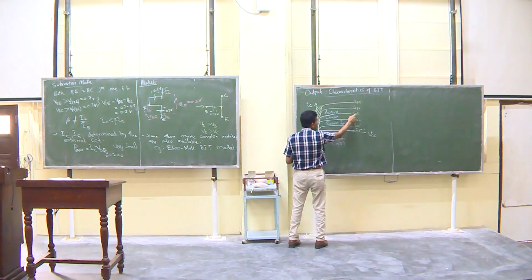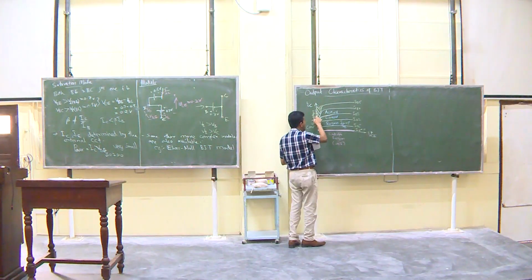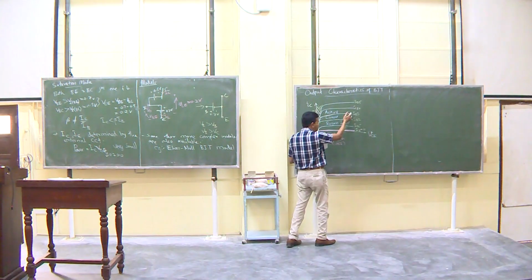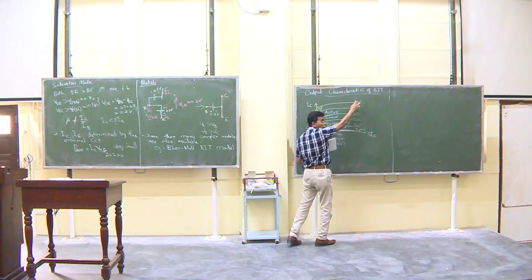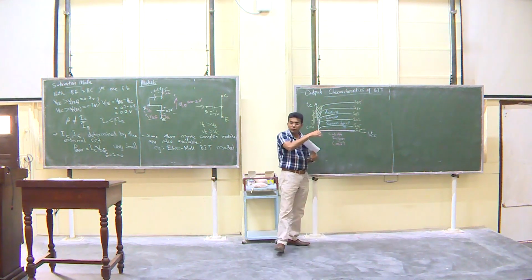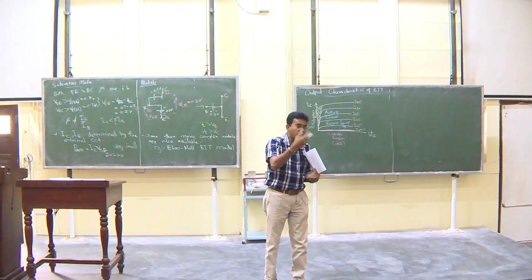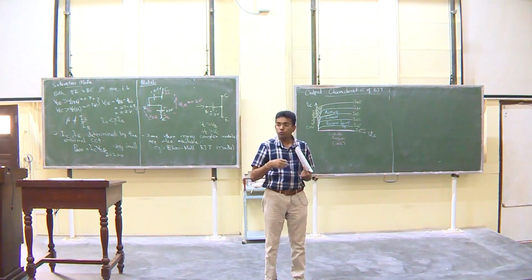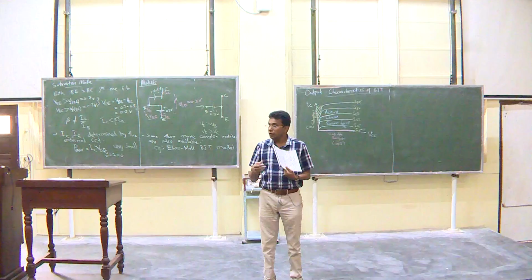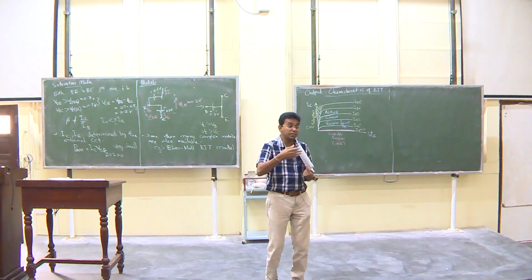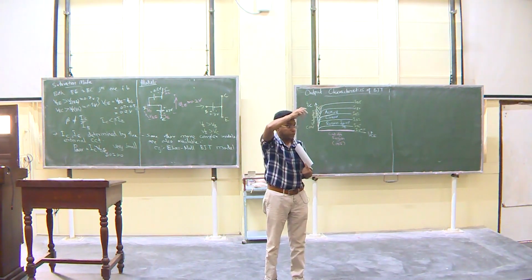IB, which is basically a constant, divided by IC divided by this. So, if beta increases, that means instead of IB being constant, IC will be more than that, right. When that happens, even more current flows. That means more power is generated, more heat is released. When you release more heat, temperature will go further up.